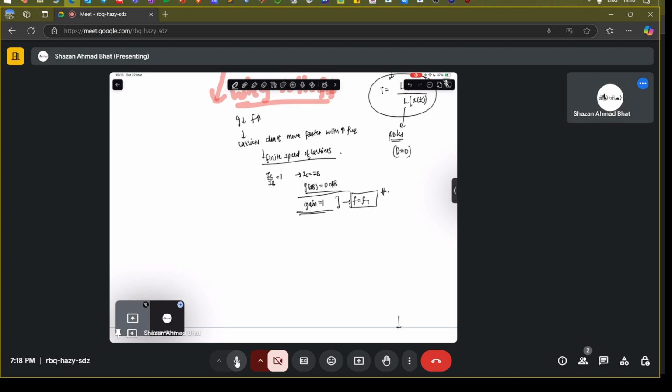Now what happens if we look at this FT unity gain frequency with increasing collector current? We see that it should go on increasing, then it saturates. But what happens is that it goes on increasing and shoots up, then it starts to reduce. This reduction is because of high injection effects. It's basically the Kirk effect, which we talked about in the previous slide.